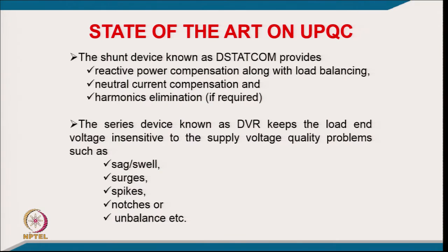Then the switching losses in the devices increase, and the thermal design of the converter also has to be enhanced: the heat sink size increases, along with cooling fans and so on. So, cost is certainly affected. The principal circuit looks the same, but the rating considerations differ.